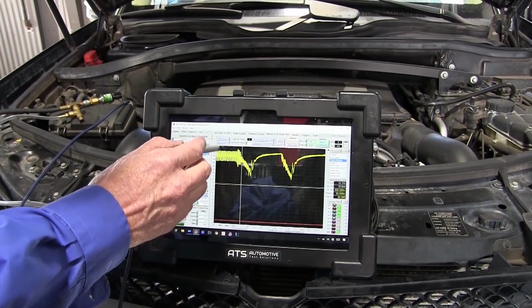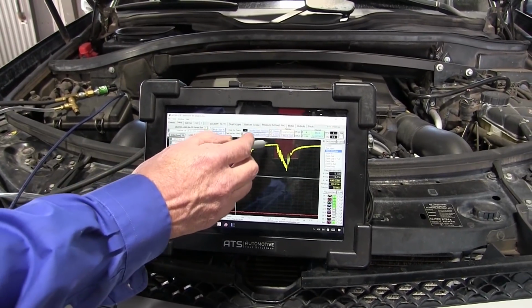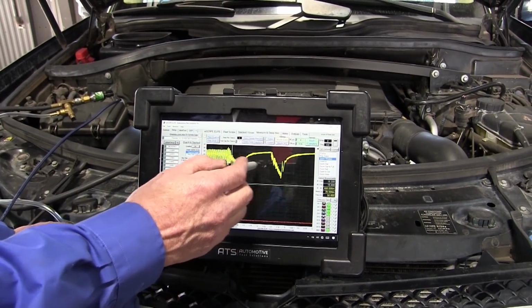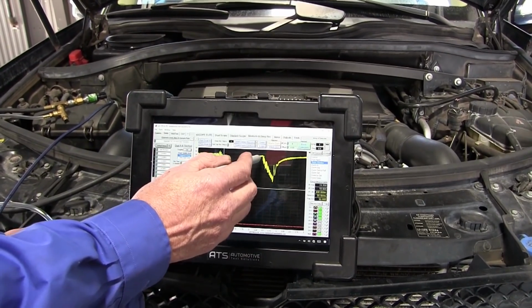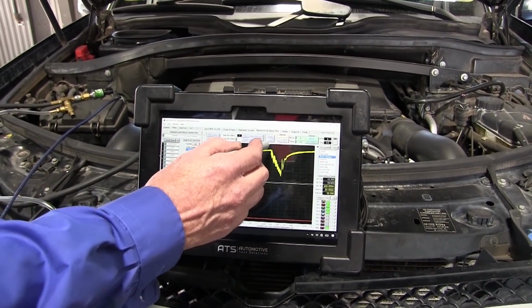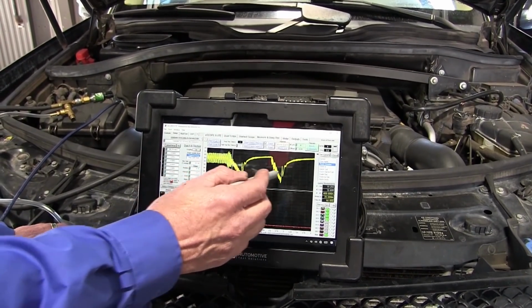Okay, we can see right here where we're dropping pressure every time an injector opens, but when I rev it, look at our drop. Build up. The injectors aren't pulsing right here because we're in a fuel cutoff from decel. That's why you don't see this. Now we open it up and it drops again. We're dropping the fuel pressure. It can't maintain the volume.